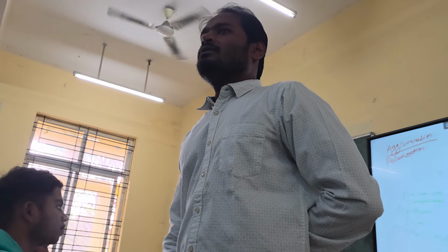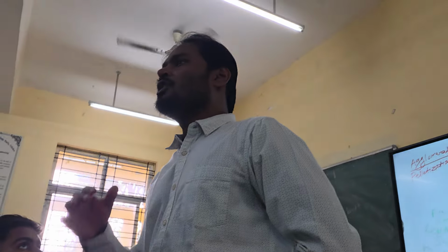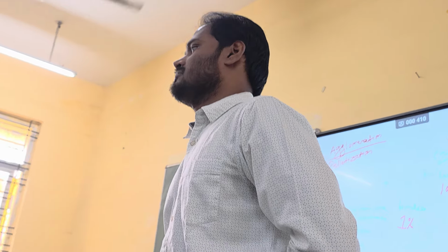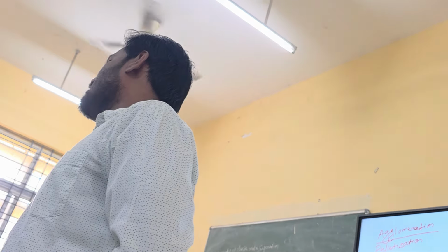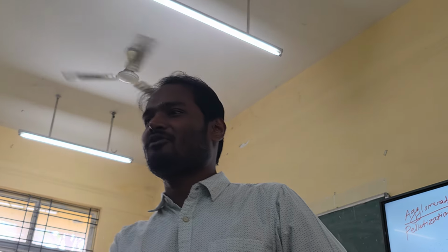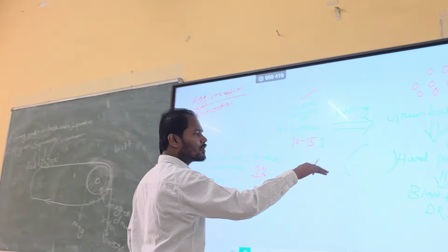Right? So you can also write what is the advantage of using agglomeration: you can utilize very fine particles, or you can say you can utilize very low grade ore also, technically. Because they need extensive liberation, so extensive grinding is required. So obviously particles become very fine. You can use the pelletization process also in that. So that is one of the advantages. Okay, fine, this is clear.